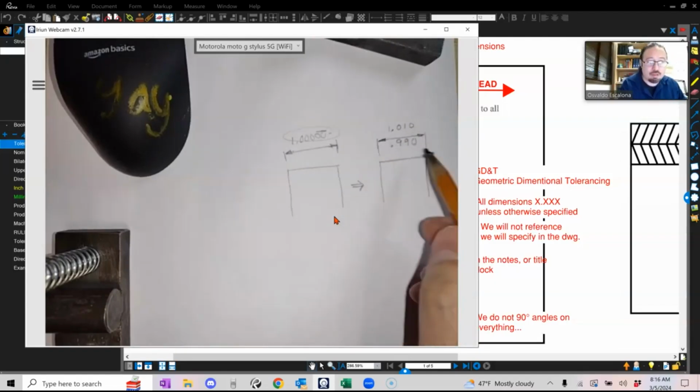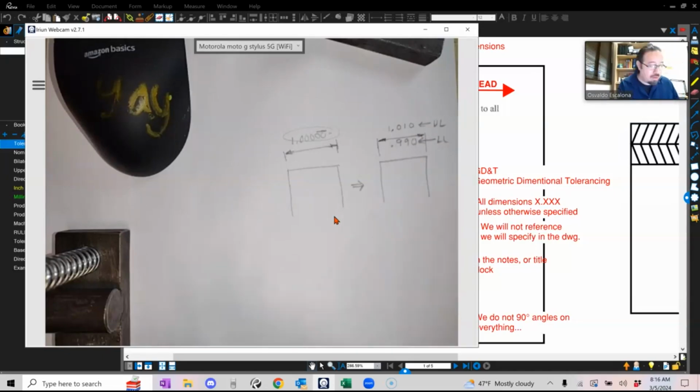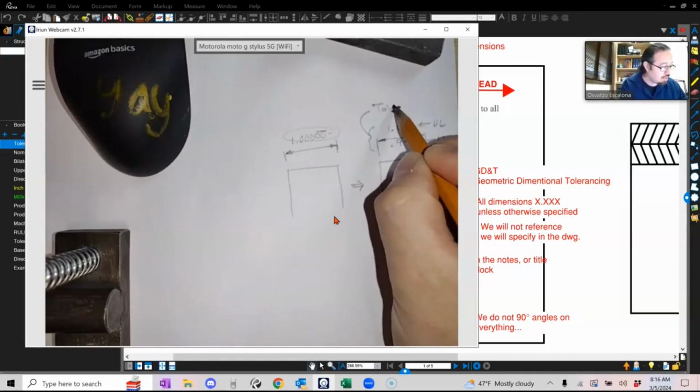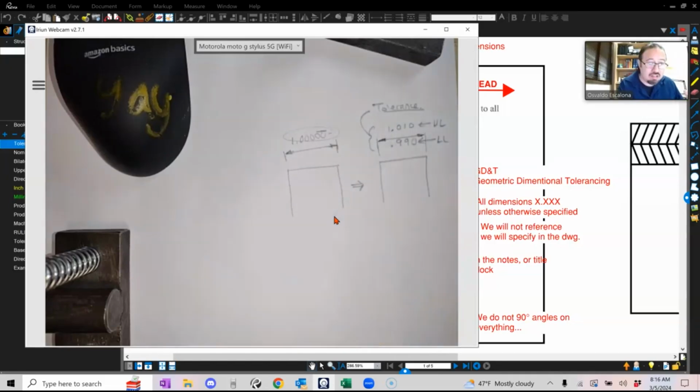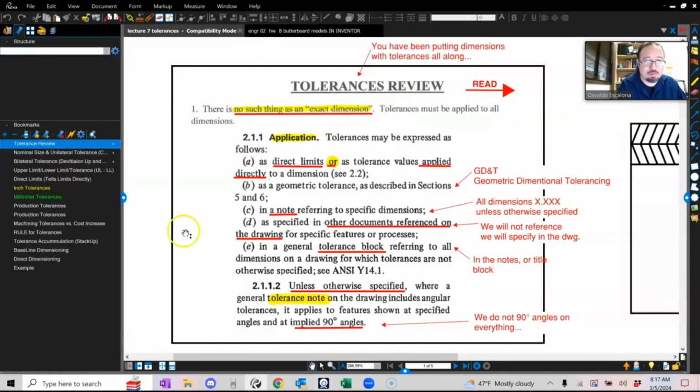If you guys were to create a bunch of them, you would have a lower limit and an upper limit. Your lower limit is the smallest I can get and the upper is the biggest I can get. But there is a little range of what is acceptable for you in terms of function. This acceptable range is what we call a tolerance. Tolerance is how much leeway you give them such that your part still functions correctly. But again, you want to give it as large as possible so it's easier for them to fabricate. It makes it cheaper. So you want to give this tolerance as large as possible to meet function. And let's actually start talking about it. There's a bunch of things that I need to go through.